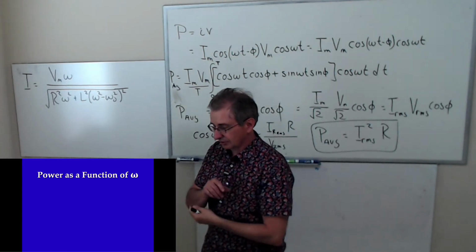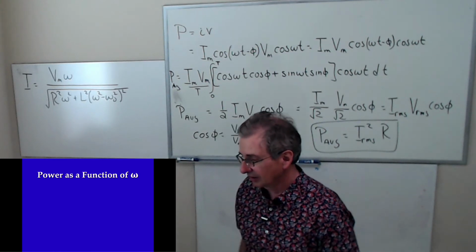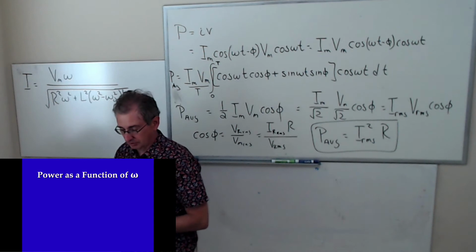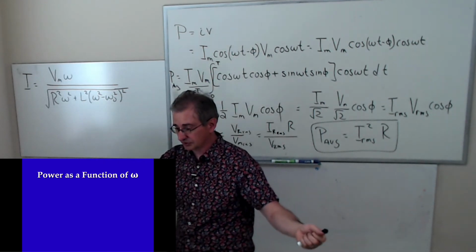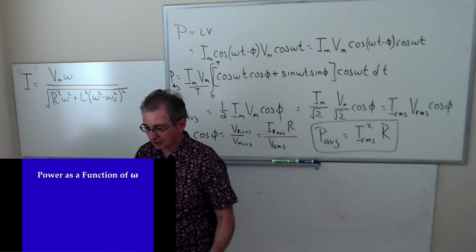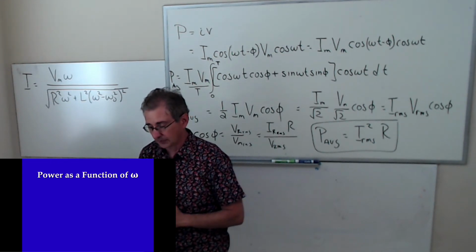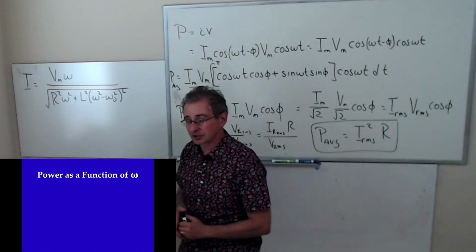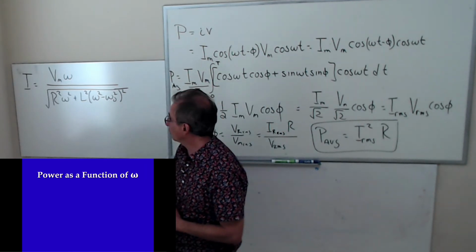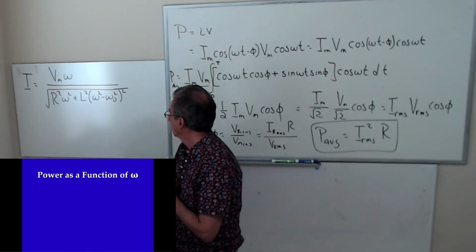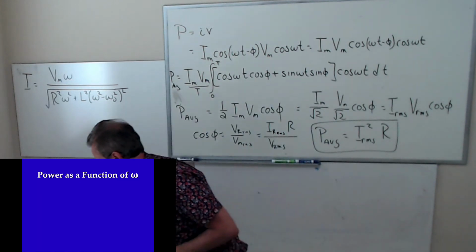Yeah, so when you start getting to extremes, the resistor will start exhibiting either capacitive effects or inductive effects. No components are ideal. So when you start going to extreme frequencies, you have to worry about what are called parasitic capacitance or parasitic inductance in any component. We're not going to look at those here, but if you're an electrical engineer, you do have to worry about that kind of thing at very high frequencies. And we're not going to worry about that here, though. Okay. So I wrote this morning in lab. So I want to look at the equation for power now.